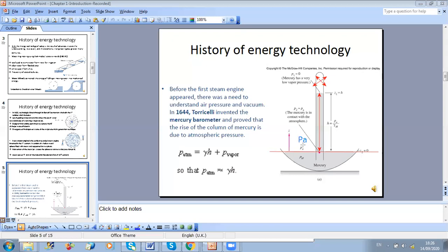Here we know it's atmospheric pressure, but if we have a suction in a room and want to determine the pressure, we can take this device, and this height will change depending on the pressure at this level. Measuring h allows us to find the pressure in any space. So this is the concept of the barometer, which allows us to measure pressure.